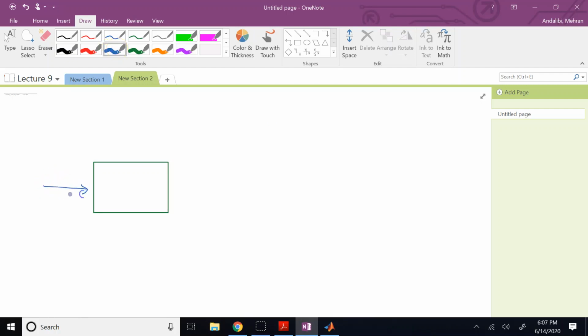One is the force of the hydraulic cylinder, the other one is, as always, gravity. Then we have the normal force from the conveyor or the flat surface below it, and then friction backwards, right, because it is moving to the right. And this friction is, since it's moving, clearly it's F sub K, or kinetic friction. So this is my free body diagram.